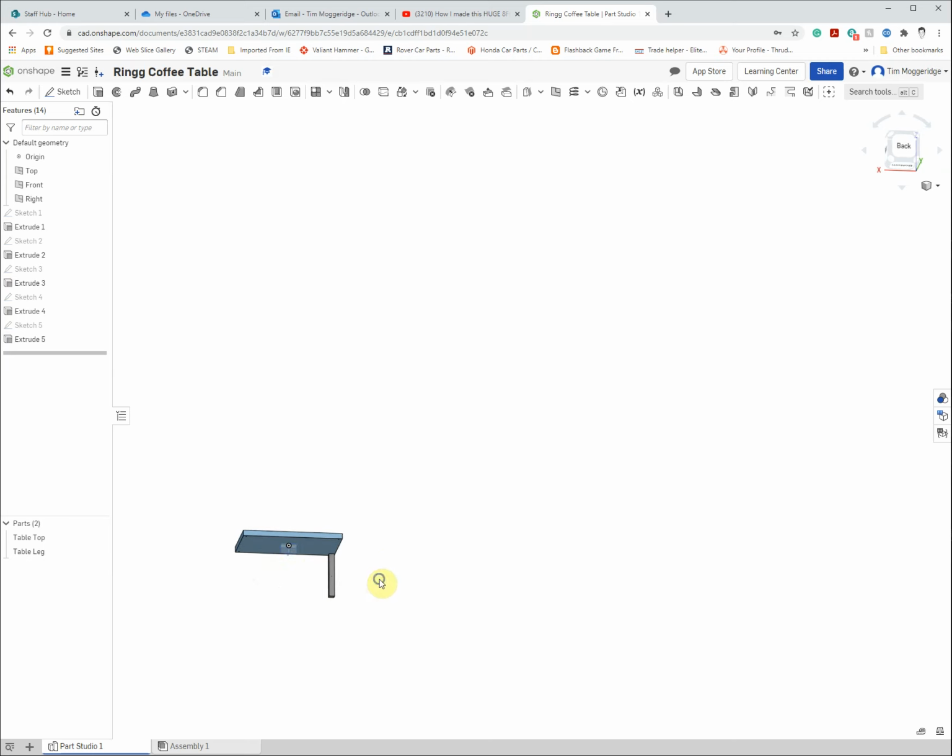That would normally appear lower down, and it makes sense to perhaps try and draw that there. So what I'm going to do is create a new work plane. At the moment I've been using the top work plane or surfaces that I've already modelled to create sketches on. This time I'm going to create a new work plane. To do that I'm going to use the work plane tool, which is this one here.